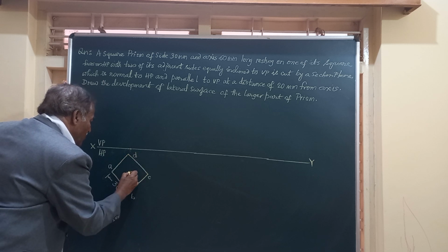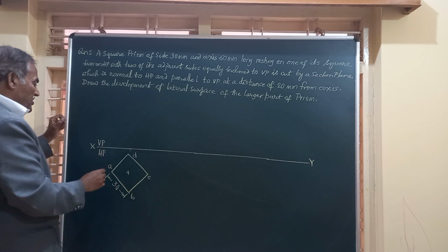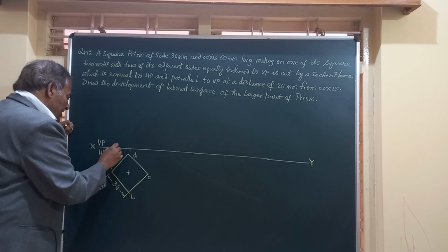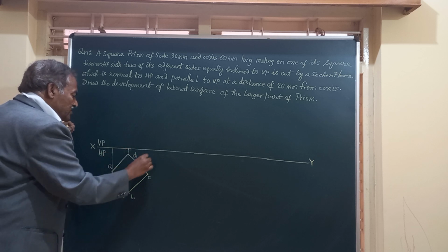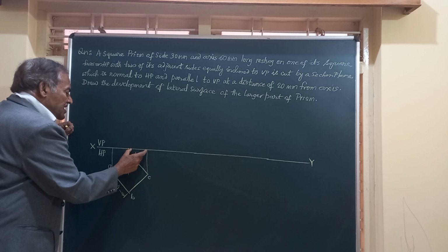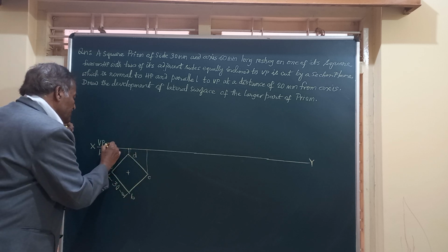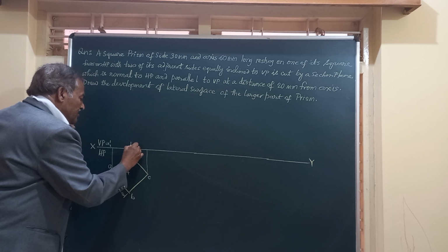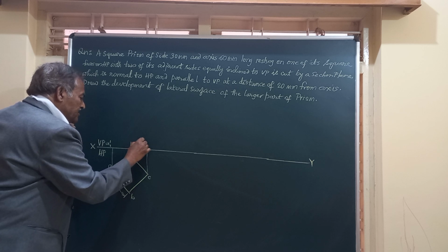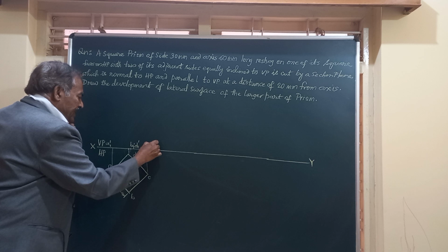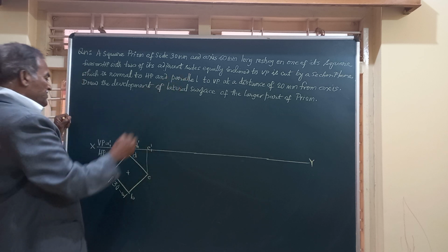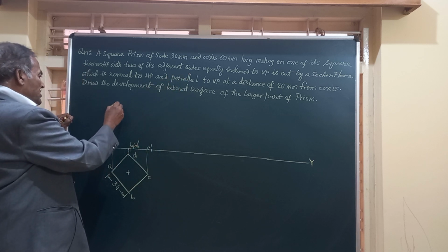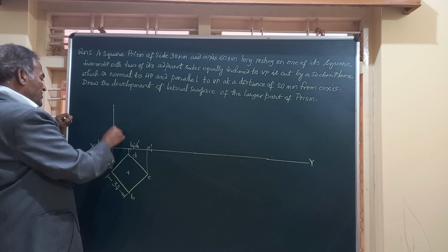And the center is O. So friends, here I am going to get the bottom face in the front view by drawing vertical lines through all these. Remember, this gap and this will be the same. This becomes A1 dash, this is B1 dash, D1 dash, last point is C1 dash. And we know the height of the solid, so to the given height we will obtain the front view.